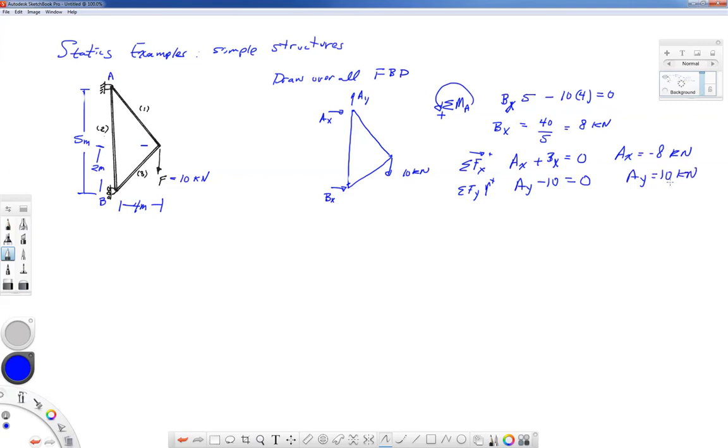When you do your statics, again, you start with a free body diagram. We just talked about that. But I also strongly recommend that you put in your sign convention for your summation of forces and your summation of moments, so you don't get confused as to which way you're calling the positive direction for the summation or the negative direction.